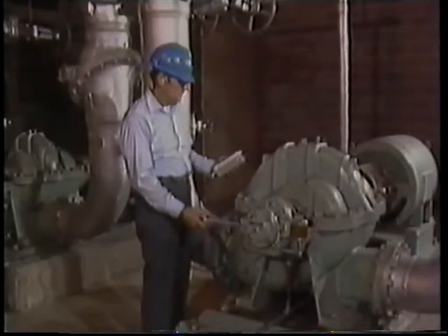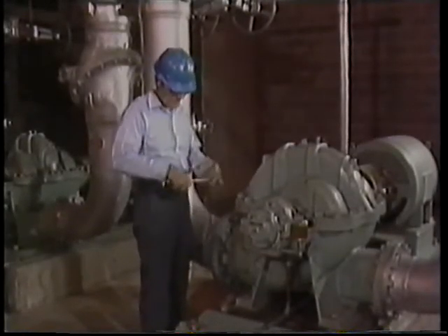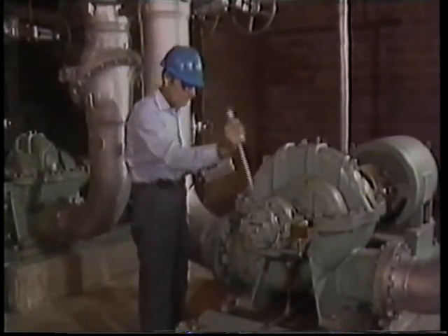Now that you understand the basic concepts of displacement and velocity as they refer to vibration, let's see how they're related. We'll use these simplified drawings to illustrate certain points during one revolution of a shaft inside its bearing. Here, the shaft is at the center of its rotation. Displacement is zero, so velocity is at its peak. Here, however, the shaft has reached the limit of its travel. It must stop before moving in the opposite direction. So velocity is at zero, displacement is maximum.